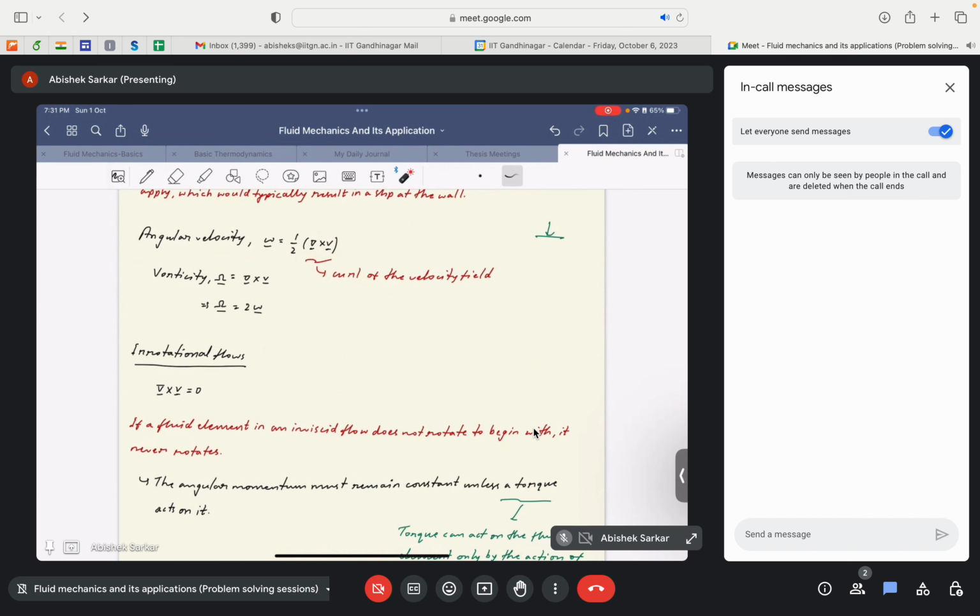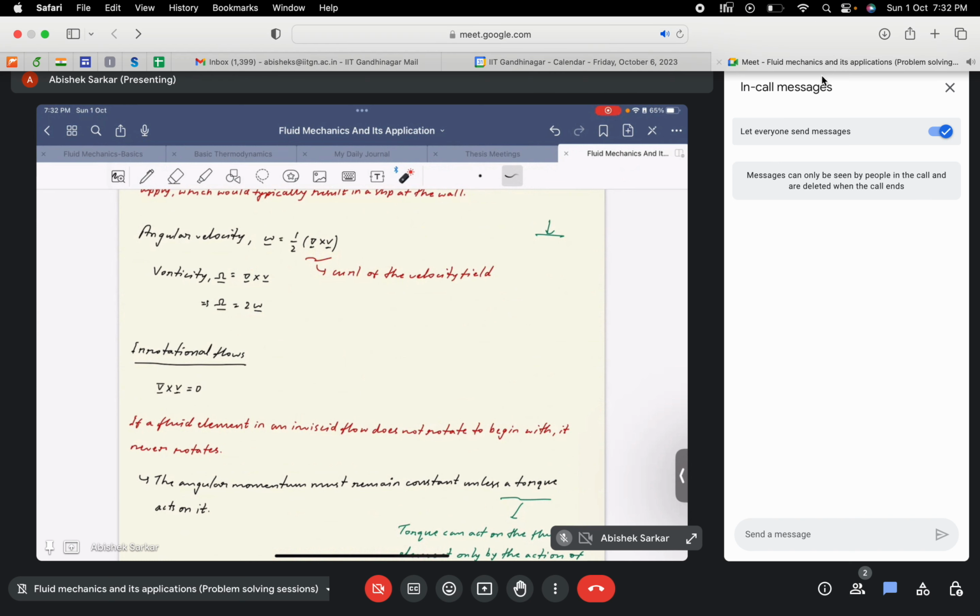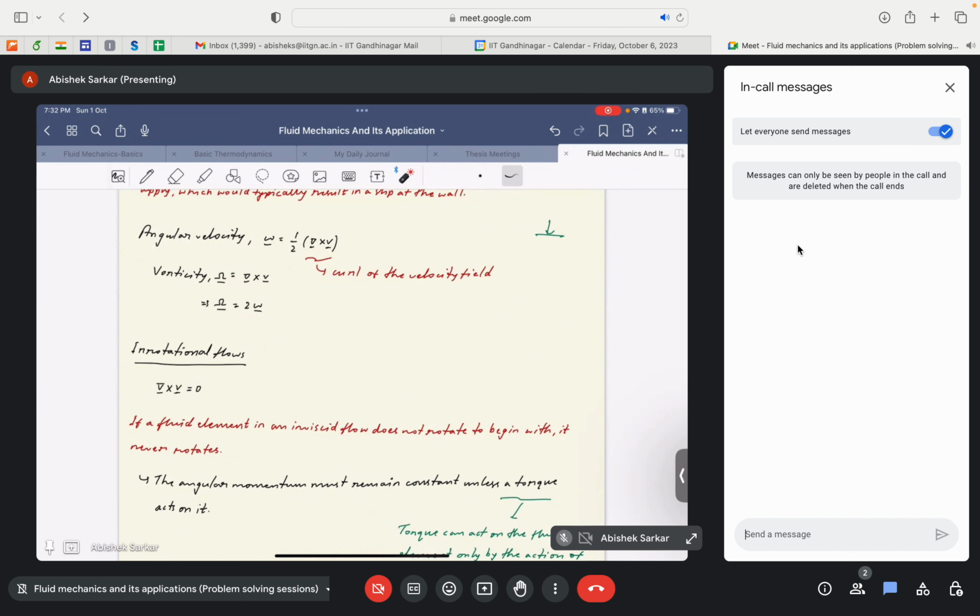Similarly, the vorticity, which is denoted by omega, is by its very definition equal to the curl of the velocity field. And you can clearly see here that the vorticity is actually 2 times the angular velocity of the fluid particle. How this is derived, how the rotational elements are derived, and how we reach this final form of the equations is discussed in a very detailed manner in the video lectures. I would suggest that you go through it so that you get a proper idea of how these terms are formed, and how to visualize this rotation of the fluid element.